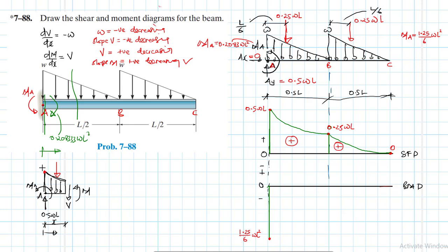Then this point here is W. Then I need this point now. So I'll need to find the equation that governs this loading from A going down. If I write it as q(x), q(x) is going to be equal to the gradient, which we know is negative, so minus the change in y, which is W, divided by the change in x, which is L over 2. Writing it out, it becomes minus 2W over L. I just brought a 2 on top.